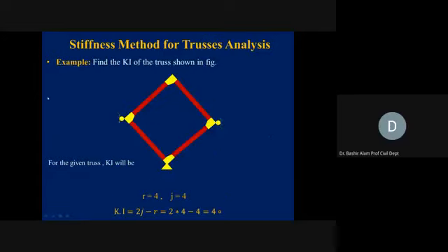So next, if we look at this structure, this is again a pin jointed frame. At the bottom, we have a hinge support. At the top, the joint is free. At the left, we have a roller support which can slide up and down the screen. And to the right, again, we have a roller support which can slide up and down the screen. Now, this top joint is giving us 2 degrees of freedom, horizontal and vertical. So we have 2 degrees from the top joint.